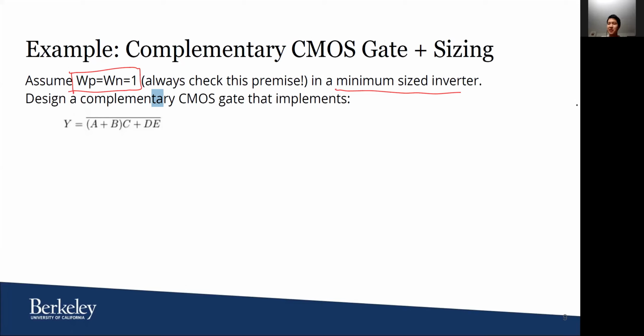Okay, but what does that really mean? If you think about an inverter sort of like this, R on P. Resistor, the resistors are the same. Yeah, okay. So let me finish drawing this. Okay, so what this means is that R on P equals R on N. All right. So that's very important to figure out when you first do a problem like this.